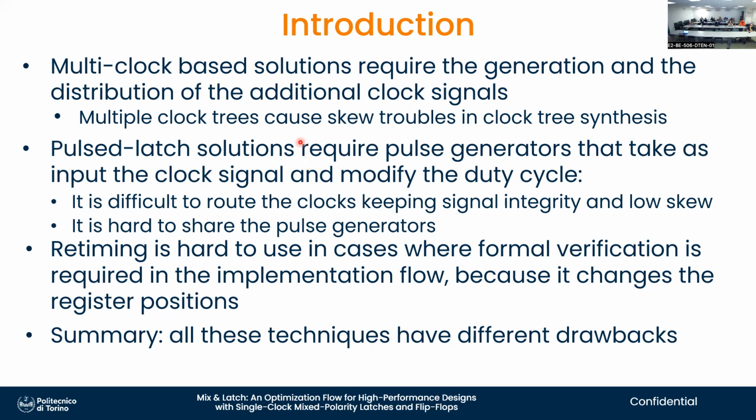problems in clock tree synthesis, as I was saying, when you need to lay out the wires physically on silicon. Pulse-based solutions use only one clock, but require precise pulses generated locally, which is difficult to do at high clock frequency.